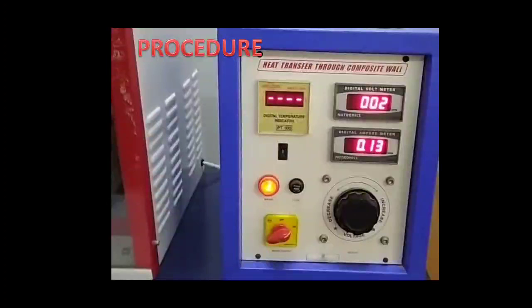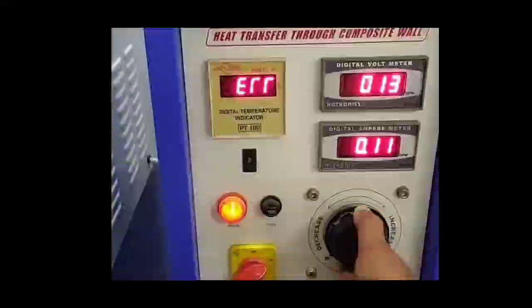Procedure. At the beginning, we have to ensure in the setup that all the mains is off, and the red color knob you can see here, which supplies electricity to the control panel, is also off, and the thermostat is rotated to the extreme left. That means in the 0 position, the thermostat supplies input to the heater. Then we have to switch on the mains, and we will switch on the red knob to supply electricity to the control panel. Then we will rotate the thermostat to give the heater input.